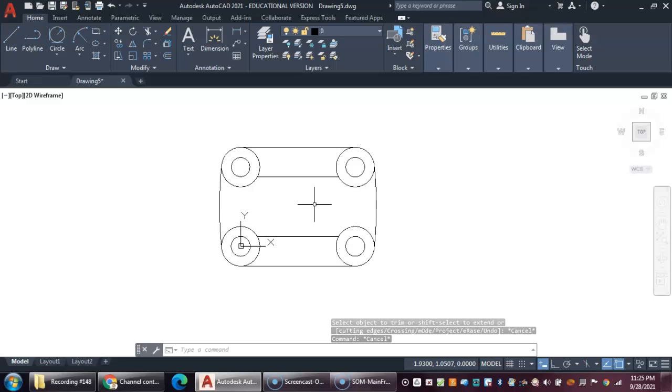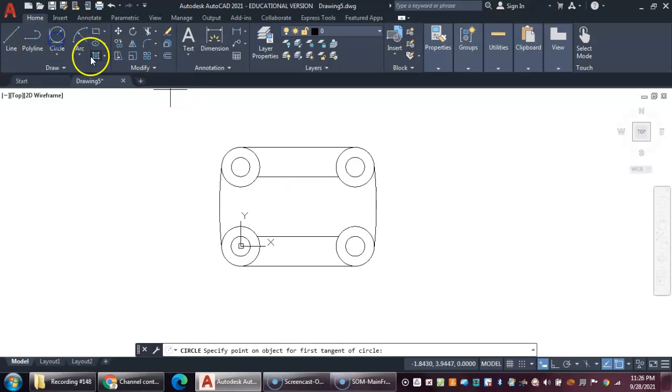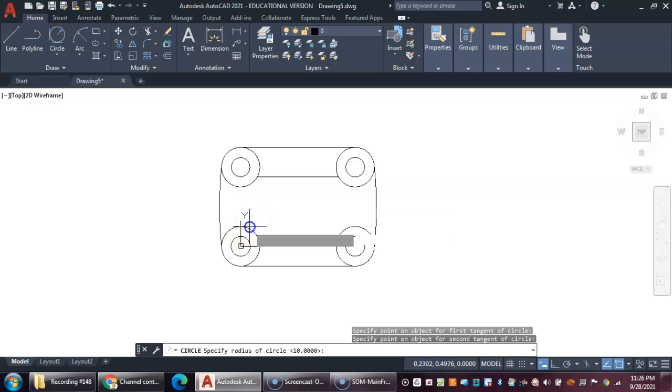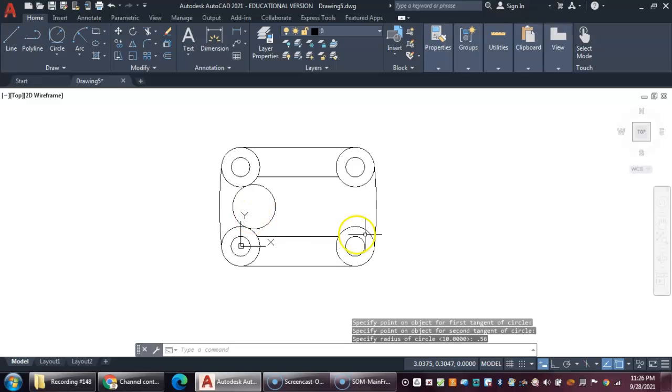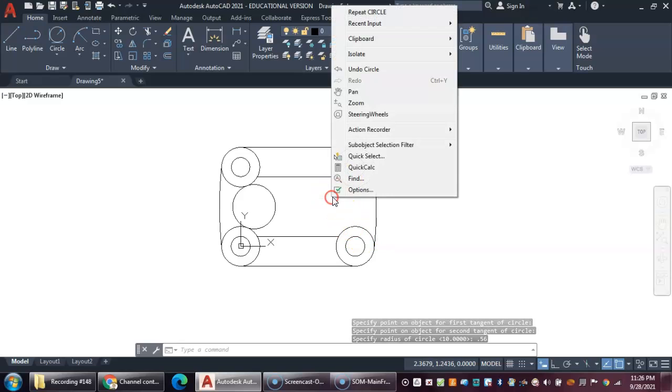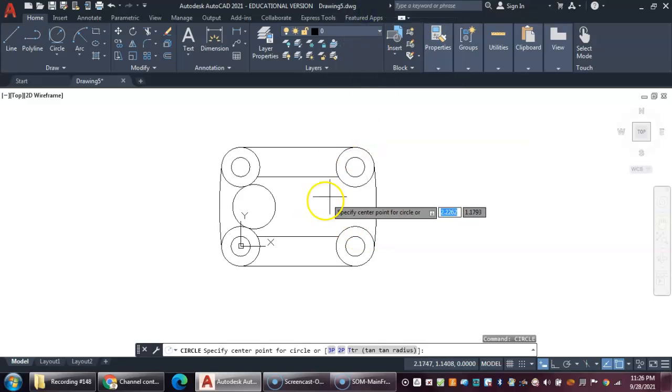Now, so we've got a 0.56 radius. That's 2 times as well. And from the looks of that, that is also another tan type situation. So let's go ahead and create the tan. So we're going to go tangent to here, tangent to there, and then we will go 0.56 on my radius. So do the same thing over here. So we'll just repeat this circle.